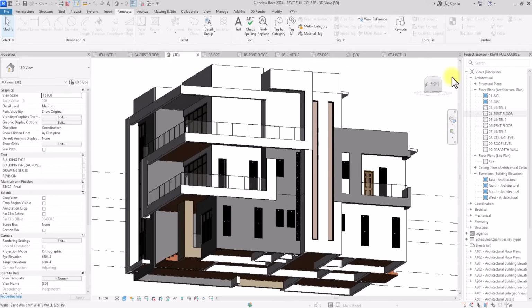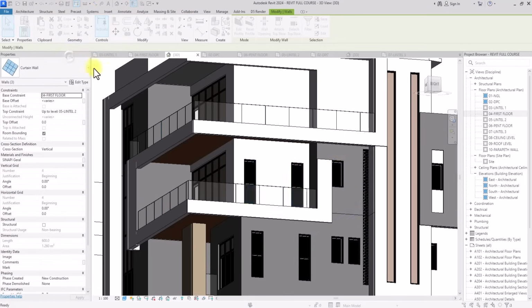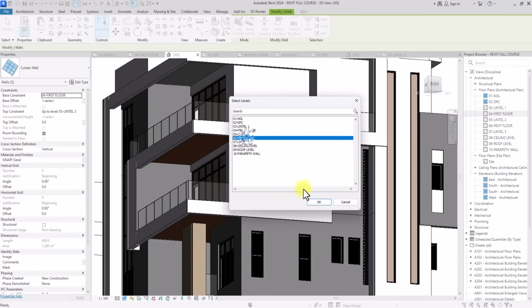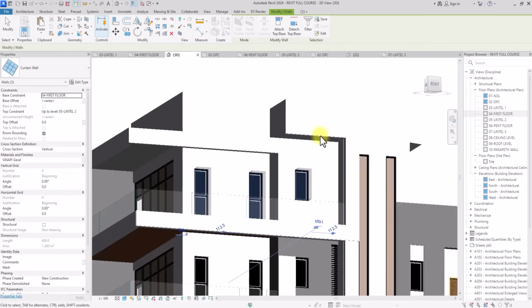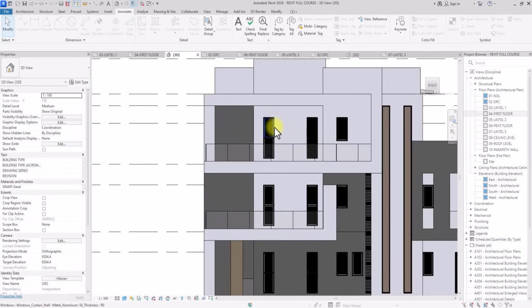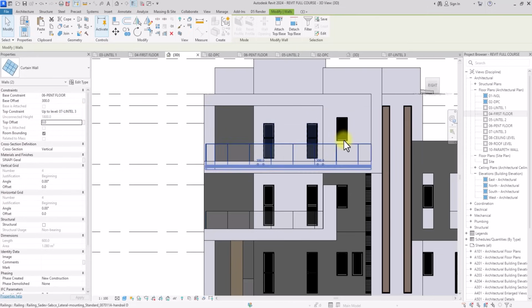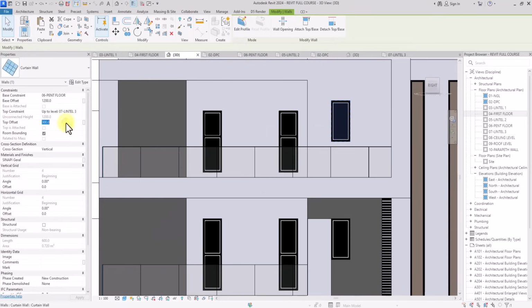So we're also going to just do the same and copy these fenestrations that are similar here. Copy this one here. Copy this and simply click copy to clipboard, and we're going to paste on the paint floor. The only issue is that the paint floor has a lower lintel, so we're going to adjust it to fit. We're going to click on this, and change this lintel. We're going to remove this offset of 300 to 0. We're also going to do the same for this, and remove it to 0.